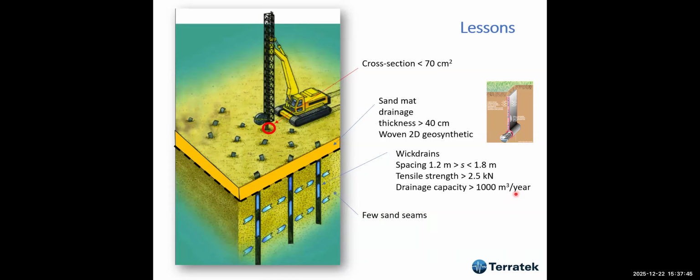And also few sand seams. In one of the embankments I've done, there were too many sand seams. At the time, we didn't have the piezocone. And later on, I knew about the sand seams because we could do, a couple of years later in a nearby site, some piezocones, and we had a project where we did all these installations, etc., and it did not work because of the sand seams. The drainage is natural, it doesn't need the wick drains.